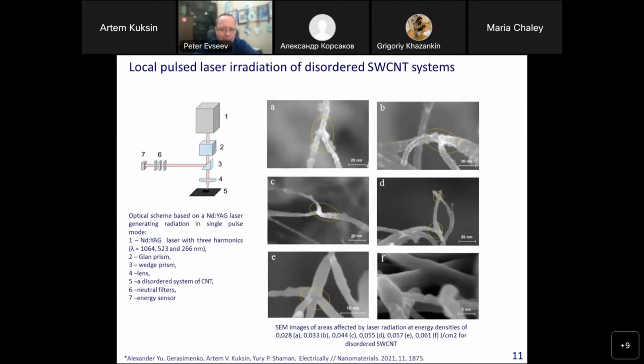Scanning electron microscopy images demonstrate the accumulation of electric charge in the region of the nanotube junctions, which can be seen by the light areas on the pictures. It's due to the low electrical conductivity of imperfect amorphous carbon junctions. We can see no such effect in crystalline junctions.